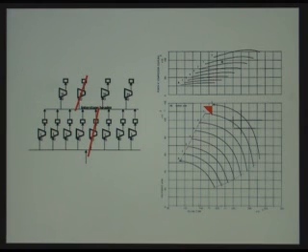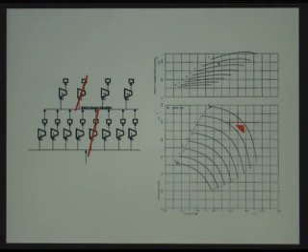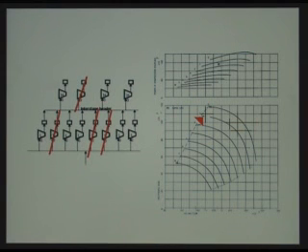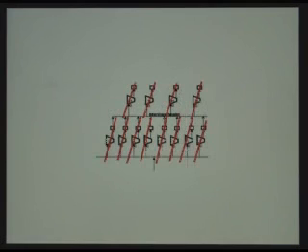Now the opposite case happened. You had minus 12.5% there, suddenly you lose 25% on the other end, the interstage pressure started to go up. So all the low pressure machines which were operating there, now they suddenly ran over to the surge line and it became a race, and the operators lost, and so two of the low pressure machines hit the surge and tripped off, and then that just killed everything. So because of that, this was handling all the gas at the facility at the time.